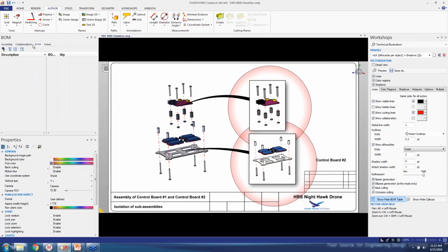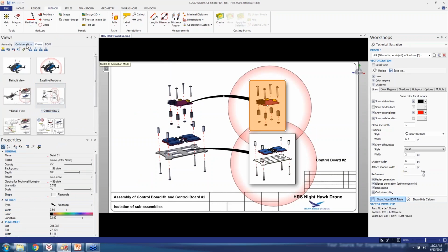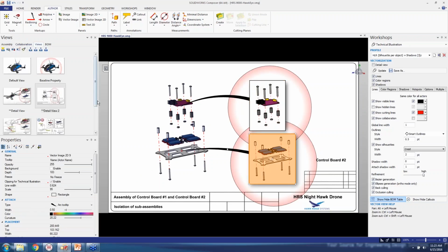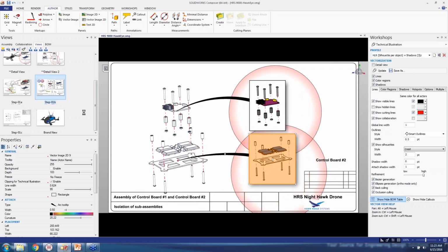If you don't name it, the easiest way to find it is to, let me pop this back here. There we go. The easiest way to find it would be to go to any view that has it, select it, go to the collaboration tree, and you'll see it will highlight here. So if it was something like this, it'll tell you exactly which one it is. So easy to find it that way, even easier to find it if you do rename it. But let's go back here.